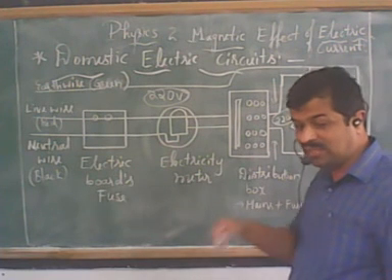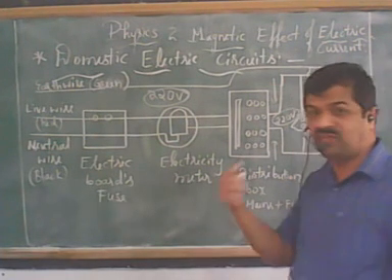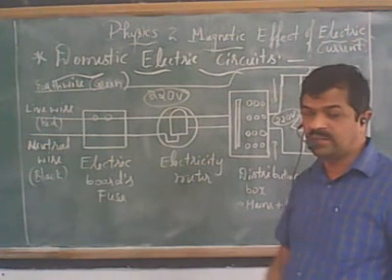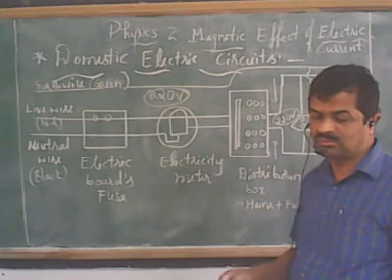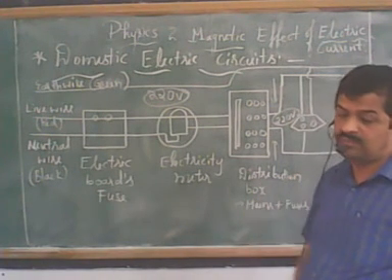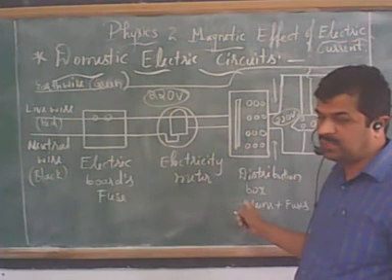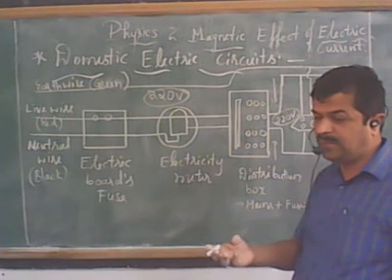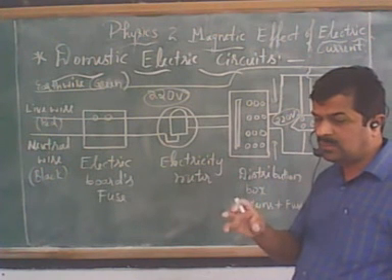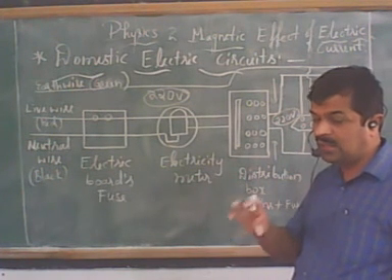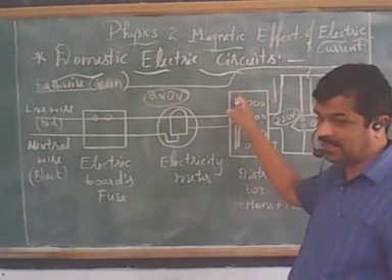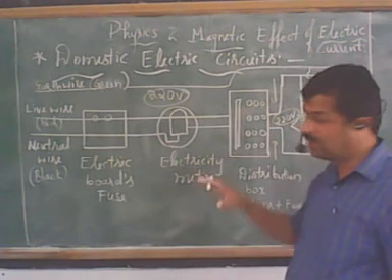For any leakage of electricity while functioning the electrical device, the electricity moves to earth, grounding, by which we don't get a major shock while handling any electrical devices which have a metal body. Very important. For example, electric oven, electric iron box have a metal body. Sometimes a grinder has a metal body. If any leakage of electricity goes through the earth wire, the green color wire, directly grounding takes place, then the system is safe.